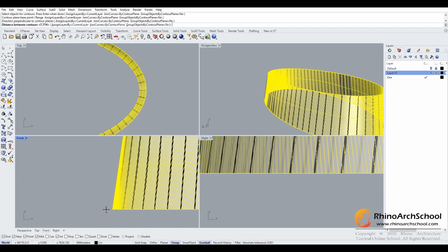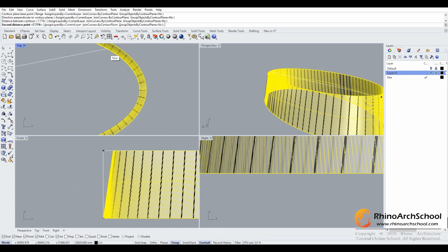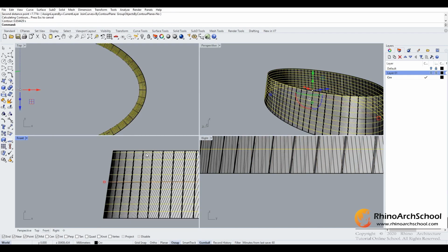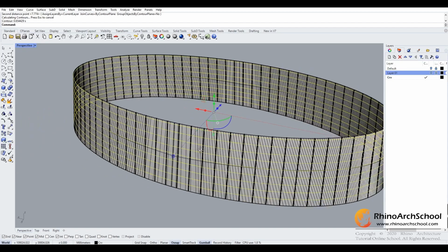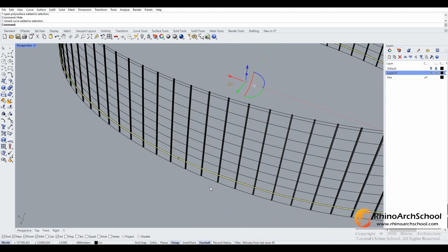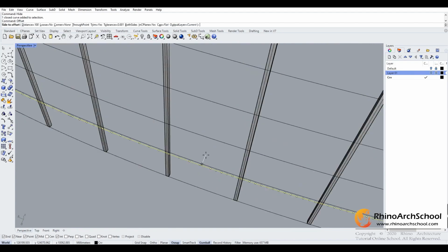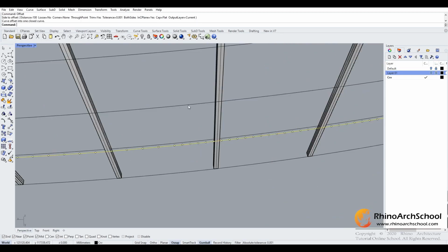So we'll set the contour by selecting the base and holding Shift and Tab. This will be the height for each windowsill. So we'll make approximately this high, and you can see it has created our contours. Now hide the surface, and we'll offset each contour by approximately 100.